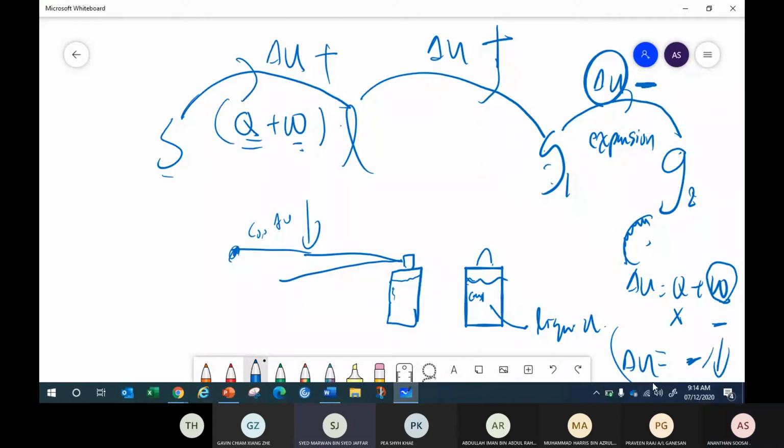Internal energy decreases, that's if there is no heat added to that gas, right? You never had heat. When you press your perfume, you are not heating it. So no Q supplied. The internal energy of the gas is decreasing. But the point here is when the gas expands, the changes of U becomes negative. Internal energy becomes negative. Okay, so that's the idea I want to emphasize here.